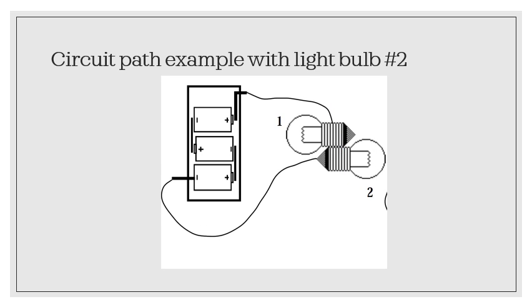In our second piece here, we've got two light bulbs set up almost the same way, but this time you can see that one of the wires is connected to the tip. So this time it's going to go like this again, up to here. It's going to go up underneath through here and out through the sleeve. This time, again, it's going to go over here. No connection over at the tip, you can see. So it's not going to go through that bulb. It's going to go all the way to there. That's the path that it will take through the bulb and through the circuit.